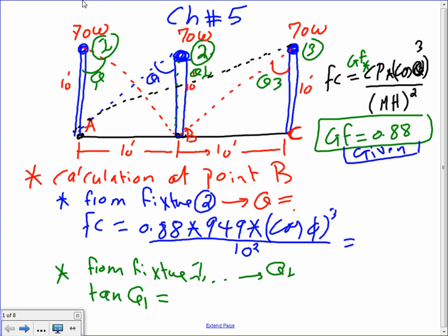That's what Visual does. You remember these brown dots that you did? That's called point-to-point calculation. Every point in Visual was 2 by 2 feet. At the corner of every 2 by 2 foot square, it will do a calculation through the whole calculation zone. This method is that calculation zone done at 3 points instead of the tons of points that Visual did. Imagine if you wanted to do that at every single point in your room. Can you appreciate Visual now and the software that we have?